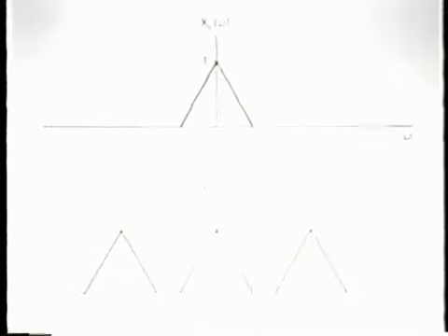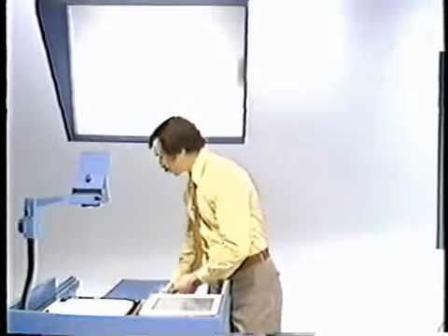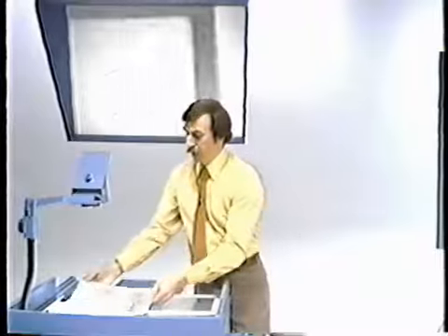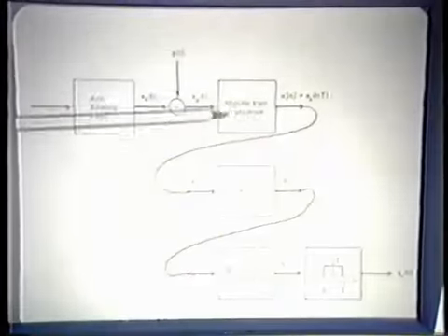And so there would be another one over here and another one over here, et cetera. And then in converting to a discrete time sequence, there is the associated frequency normalization so that the sampling frequency gets normalized to a frequency of 2 pi.